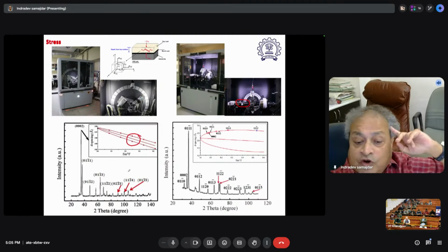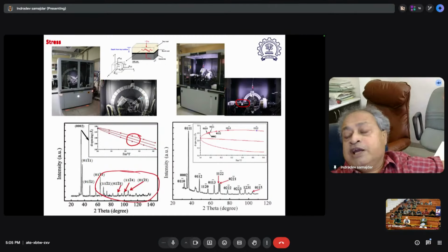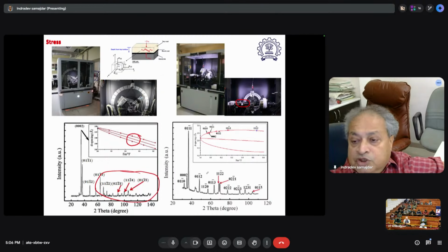This is only for one pole. If you want to make it depth sensing, like a sensor, you want to go lower and see how much is the distance from the top of the sample: top coat, bond coat, substrate, which you have been doing. You can do this in what we call multiple HKL GIXRD, grazing incident X-ray diffraction, and you can measure for all peaks.